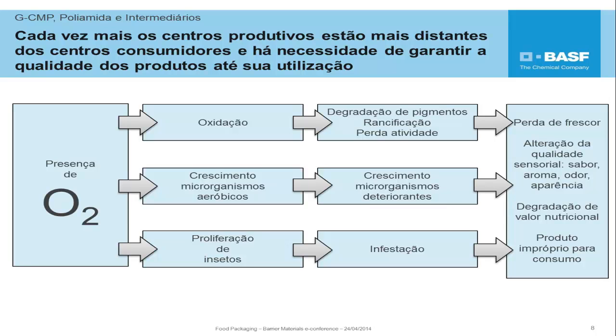If some special technologies are applied to keep food conservation, the aerobics just grow more quickly. Besides, there is also a proliferation of insects. That is why polyamide is used in packaging for storage of grains, since the smell of the beans is retained in the polyamide packaging, avoiding the attraction to insects. Therefore, we see that the advantages of the use of polyamides in the application have to do with the mechanical resistance and the barrier of conservation of those grains. These are very interesting applications for polyamides.